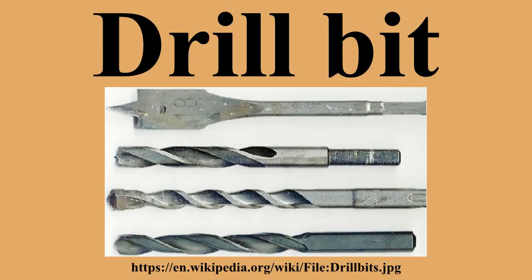In very small sizes it is difficult to fit carbide tips. In some industries, most notably PCB manufacturing, requiring many holes with diameters less than 1 mm, solid carbide bits are used.